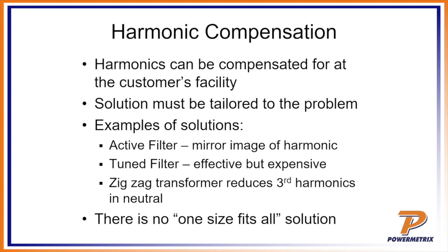Third solution was something that another fellow here that I worked with mentioned to me, something called a zigzag transformer. That's something I've actually not had much experience with, actually no experience with in my 30-something years in engineering. But basically, it's used for those third harmonics. You remember the ones that burnt down the clubhouse. So that's an effective way by which you can get rid of that.